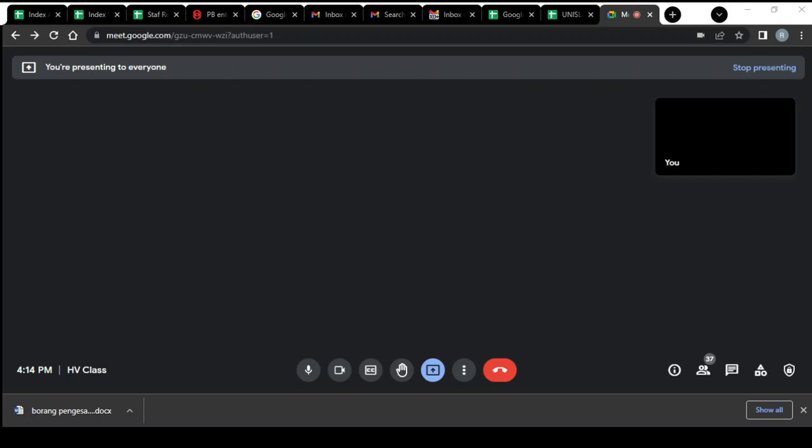All you need is the high voltage source clipped to the sample, and the other one connected to the ground or low voltage, and these values will be captured by using a software monitoring system. So you should be able to see the fluctuation of the voltage and current. Other than that, if you need your sample to be sprayed to simulate light rain conditions, obviously you need a nozzle, and with the nozzle you need a tank of water as well as a pump. That is additional, depending on what test you are going to perform.